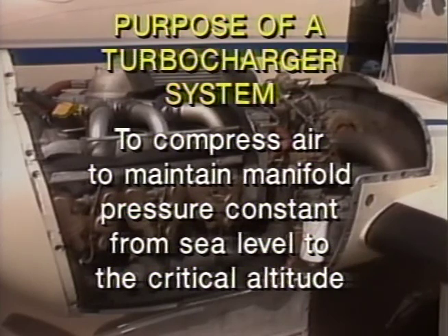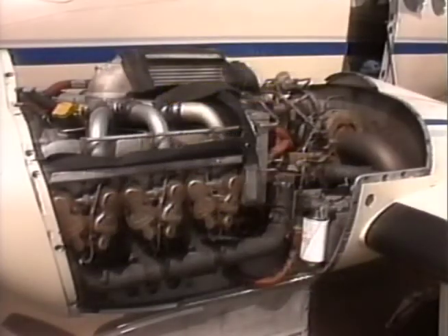Now the manifold pressure may be higher than ambient, but what you're trying to do is keep a constant manifold pressure as you go to higher altitudes. It lets you increase the manifold pressure as you go higher. Now, what is boost manifold pressure? Well, boost manifold pressure is considered to be anything more than 30 inches.